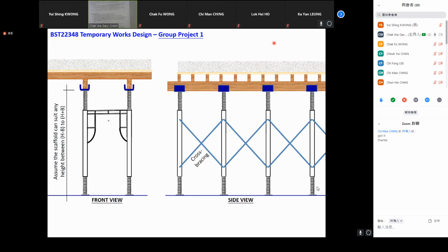You can refer to the slab formwork design example to check the plywood. And don't forget to consider the operation load, self-weight of the plywood, etc. And then you can check the joist. You can propose different types of timber as the joist, and you have to assign the spacing between the joists when you do the design. So everything is proposed by you. And for the joist design, you may take a look at hint number 2.